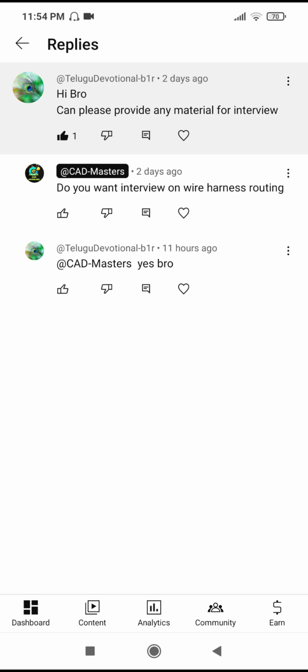Okay, all the detailing is done there: how many splices are used, where the splicing happens, how many connectors are used, and every wire connection is mentioned in the form board drawings. Then which types of tapes are used and at which locations.